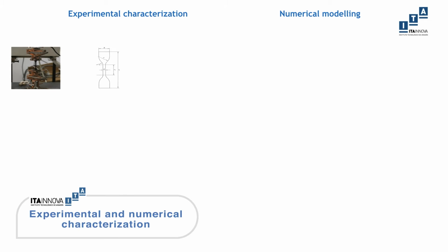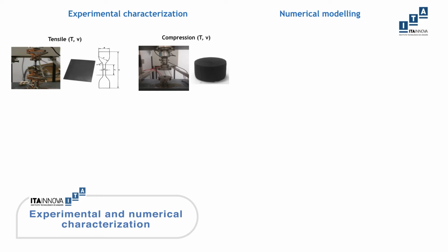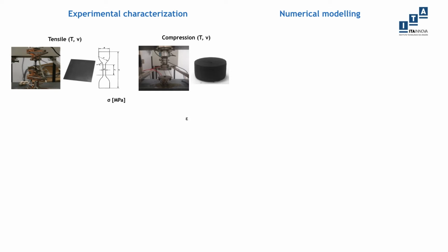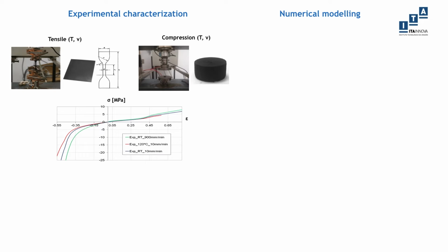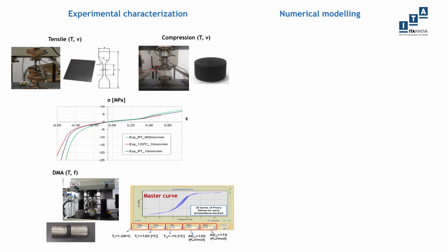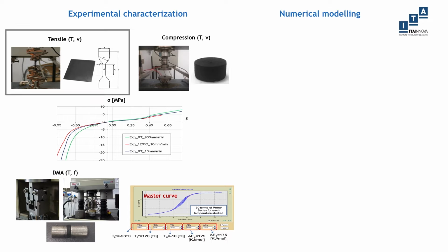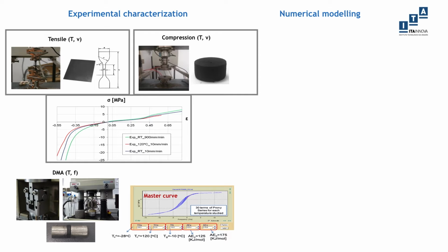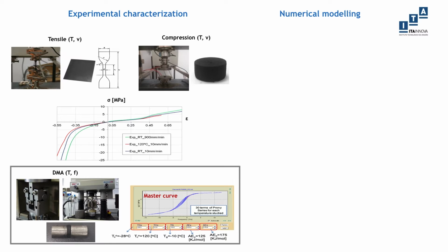The experimental and numerical mechanical characterization of the rubber is done to feed the numerical modeling of the friction behavior, where the material properties have to be numerically described. To that end, tensile and compression tests are executed once the cured rubber material is prepared in the form of rubber slabs and buttons. A dynamic mechanical analysis is also done to describe the dynamic behavior.